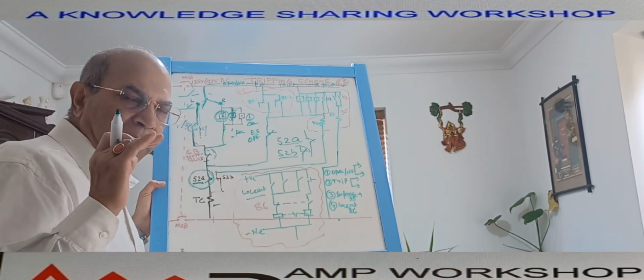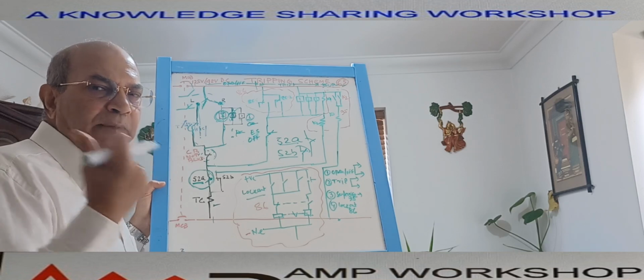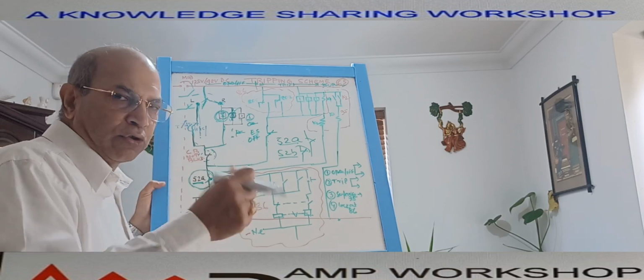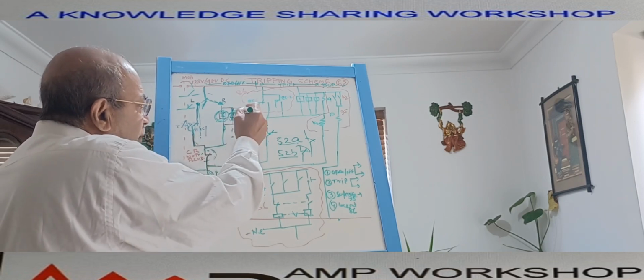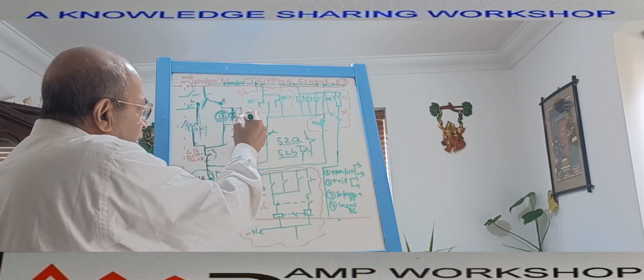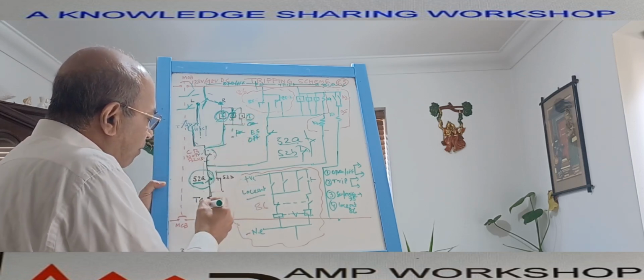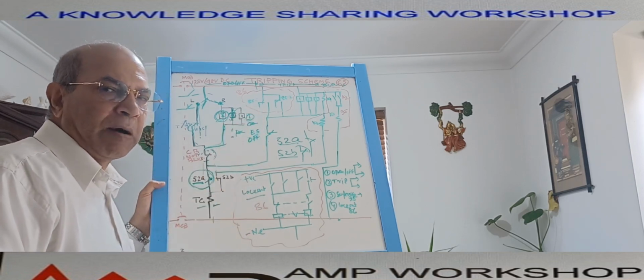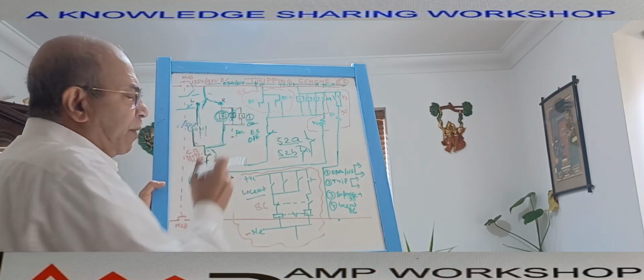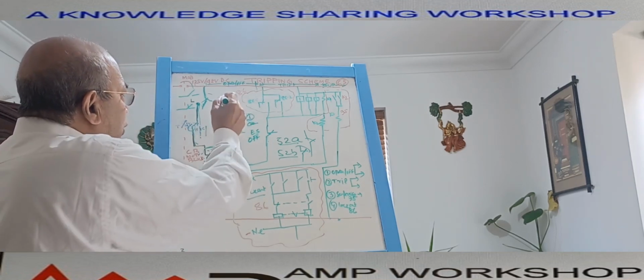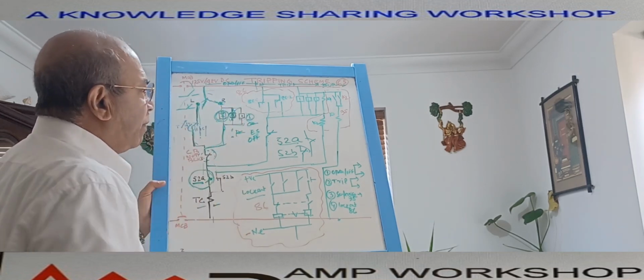In case of an electrical manual signal, we use a push button. We can give the command, or through a switch from the remote position, you can give the opening command. The moment you give this opening command, it becomes 1. Then what will happen? In the same way, the circuit breaker tripping coil is getting power. Immediately the breaker opens. So this is the breaker opening operation from the local as well as remote. So this part is the breaker opening operation.